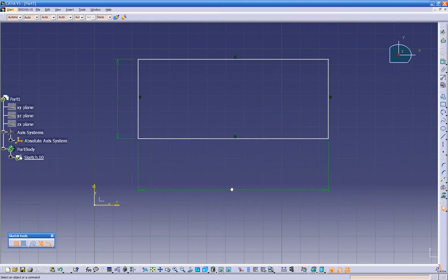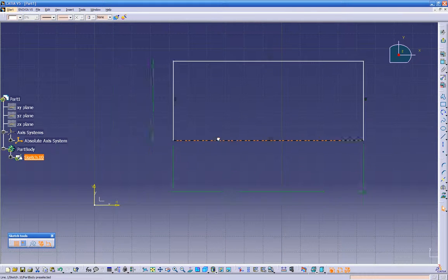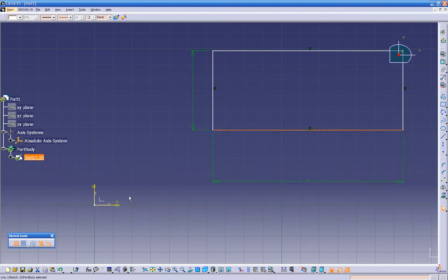and we don't have to create the dimensions anymore. It's fully constrained. The only thing that is not constrained is the axis of the sketch, which is important. So let's give it a quick dimension. See, it automatically knows it's fully dimensioned, and the moment I want to do this constraint, it knows I already have it down here.